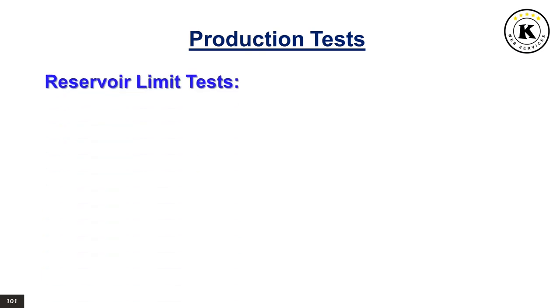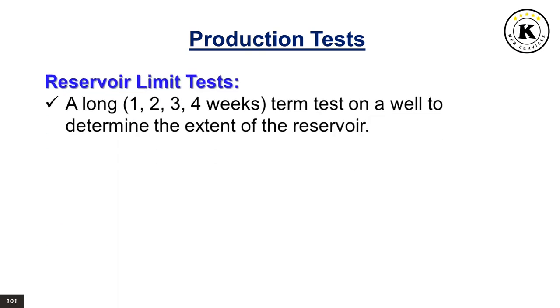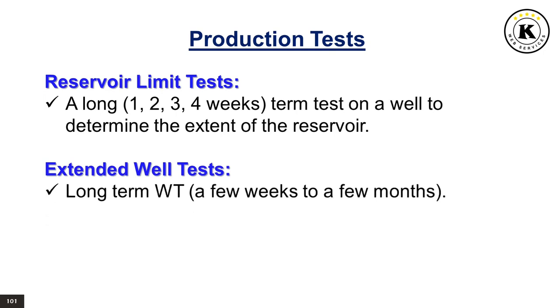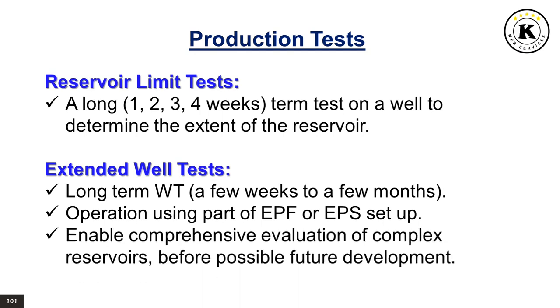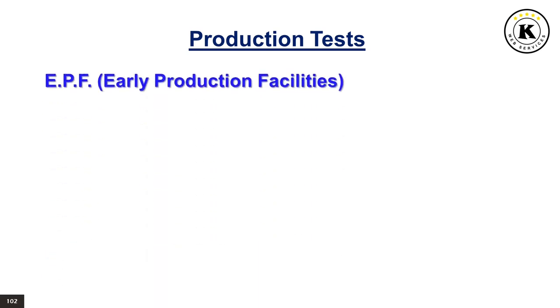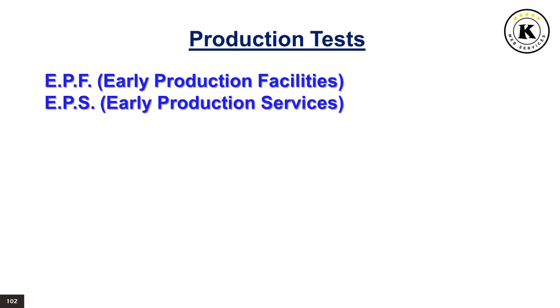Reservoir limit tests. This is a long-term well test, from 1 to 4 weeks, to determine the extent of the reservoir. Extended well tests. This is a long-term well test, a few weeks to a few months. During this type of test, the operation uses part of EPF or EPS setup. It enables comprehensive evaluation of complex reservoirs before possible future development. EPF, Early Production Facilities. EPS, Early Production Services.